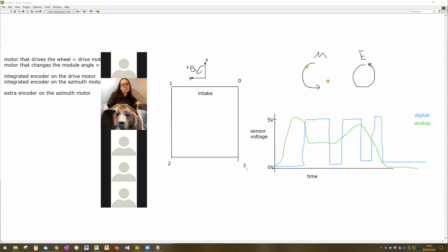So that's why the robot can turn on when you push the robot really fast. The downside is, that's really great, that's how all of electrical generation works for the world. The problem with that is we have lots of things on the robot and other robots near us that generate magnetic fields, particularly the motors. The whole point of the motor is that we're generating moving magnetic fields.